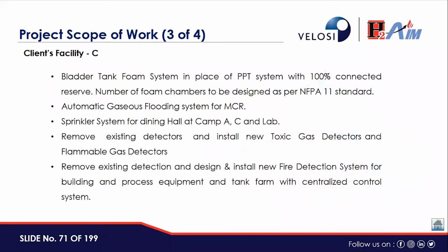Then for facility C, the scope was we have to replace the bladder tank foam system. We have to basically install the bladder tank foam system in place of the PPT system with 100% connected reserve. The number of foam chambers is to be designed as per the NFPA 11 standard. Then we have to design the automatic gaseous flooding system for MCR, and the sprinkler system for the dining hall at camp A, C, and the lab.